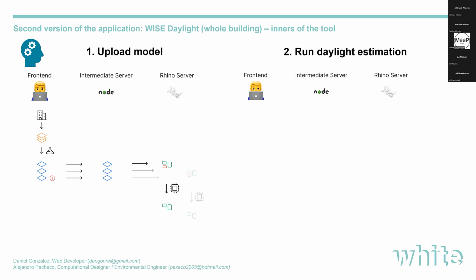We identify all the objects present in the layer, and we try to translate each of those objects to the type of object we are looking for based on the type. So for example, if you have windows, we try to translate the objects that you put in your model to windows. Maybe you put a dot, and we don't know how a dot translates to a window. So that would be the red object that I put there. And what the Grasshopper returns is a layer only with the objects that we could translate. So basically, it's like filtering the things we couldn't understand.